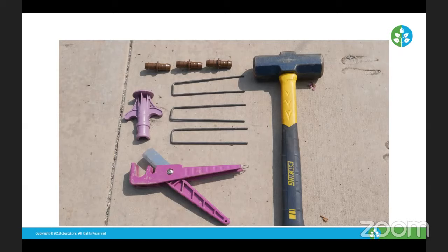During the summer, you can just leave the tubing out for a while exposed to the sun, which makes it a little bit more malleable. Or I've heard of people using a small blow dryer to heat the tubing up so it can easily slide over the insert fitting. It is barbed, so it won't come back apart.